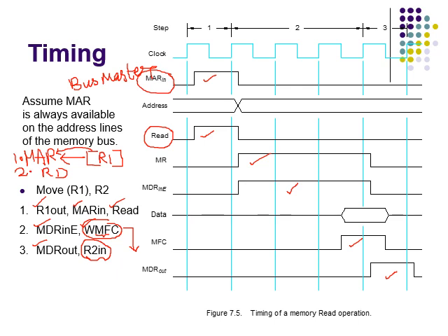So this figure shows that MDR in E is set to 1 for exactly the same period as the read command MR. That is, MDR in E is being set to 1 similar to the command MR. Hence, in the subsequent discussion, we will not specify the value of MDR in E explicitly, with the understanding that it is always equal to MR.